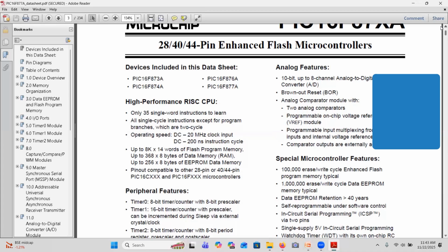So actually it is not the case. They have only one ADC. If that is the case, how will they digitize it? There is a concept called multiplexing, right? In the multiplexing register, to represent 8 channels we can use 4 bits.